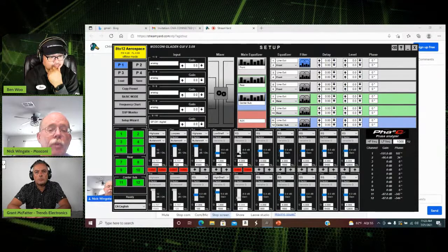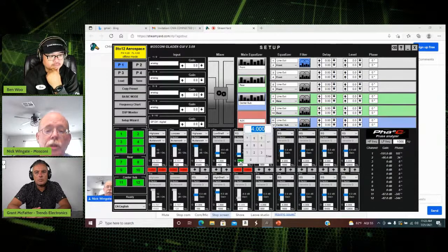Okay. Now you've noticed all of a sudden that we've turned not only 400 hertz down, but we also turned 315 and 500 down, which we did not want to do. That means we've got it to the point where it's affecting too much energy either side of 400 hertz, which means we have to increase what is known as the Q, or how much energy it is affecting.